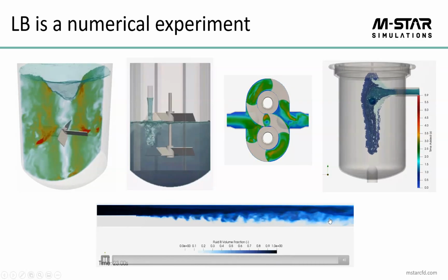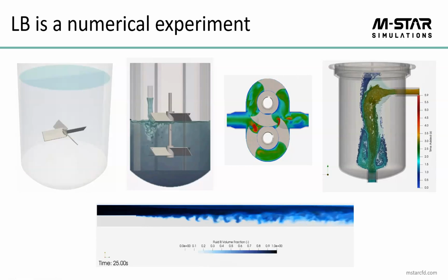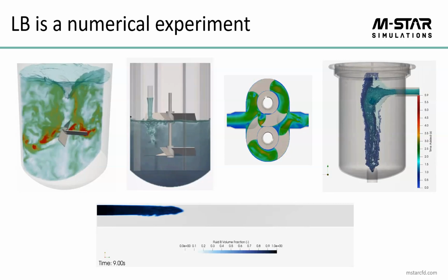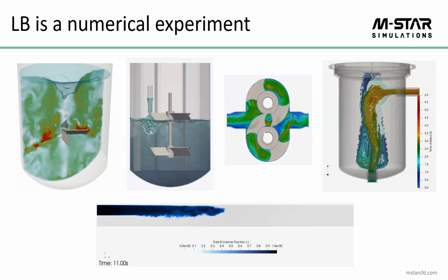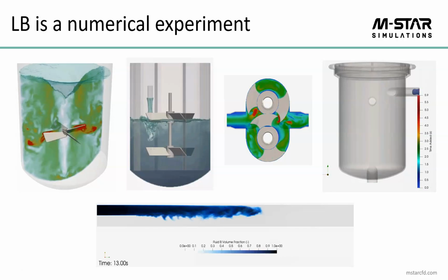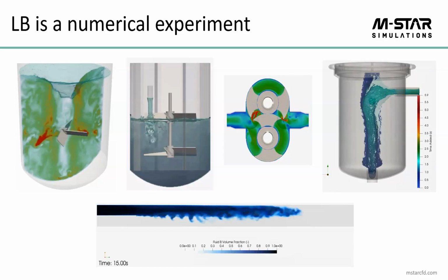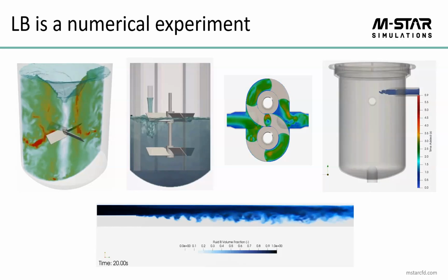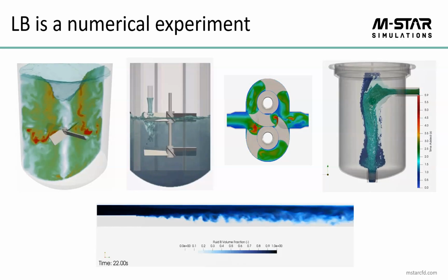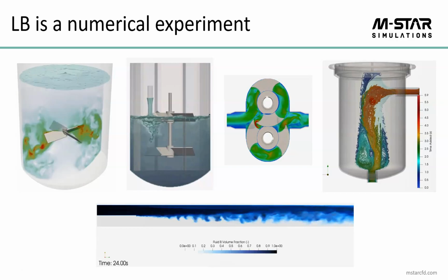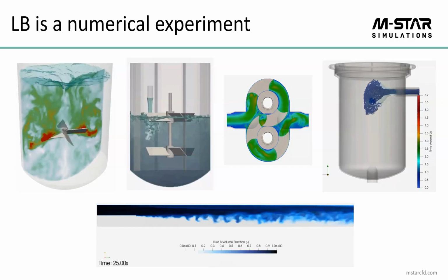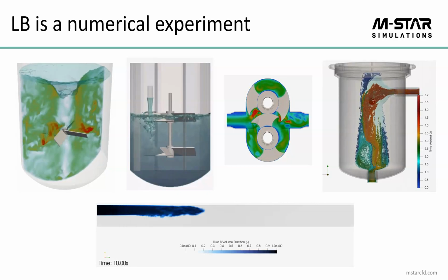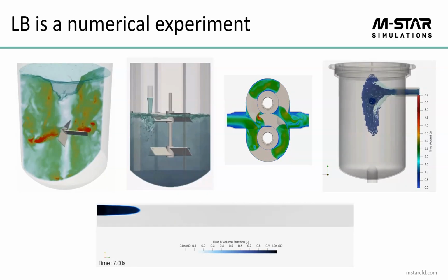And so the real takeaway point is this: we move to modern architectures and run them on GPUs. We can do things like this in minutes and hours of wall time. None of the simulations I'm showing you here took more than 90 minutes to run. That is, none of these process simulations, as it were, took more than 90 minutes to run on a 2 GPU resource. And that's the big deal, is that these things which are intractable to run using finite volume-based techniques are trivial to run using LBM techniques and GPUs.